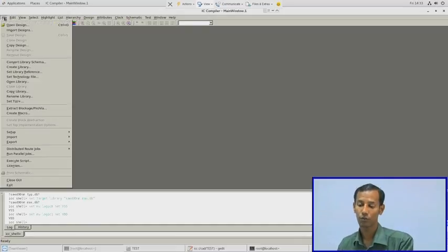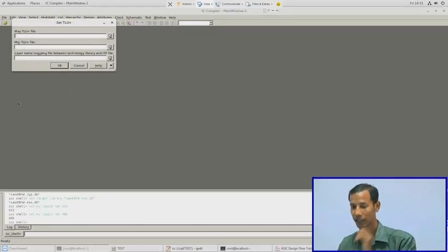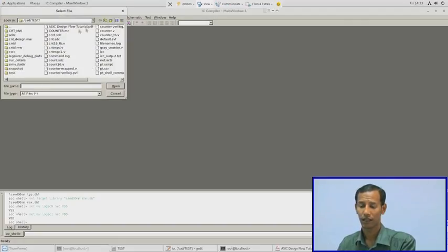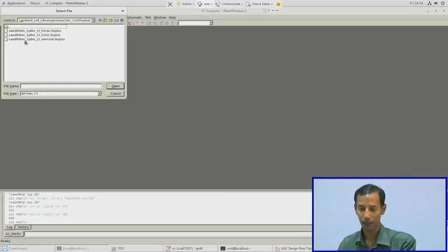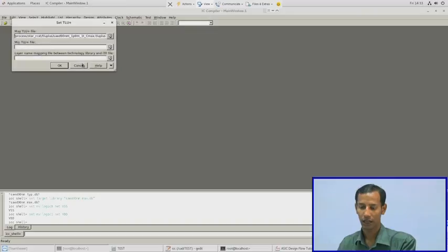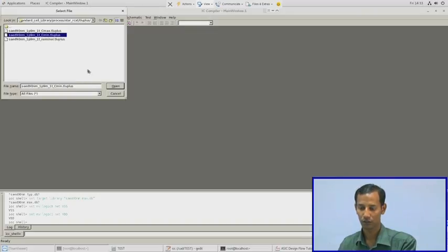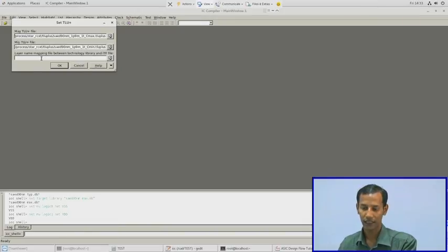After that I have to create the TLU files. These are the additional files, the library information files, which are required by the IC Compiler. You will get these in the technology library itself. In the process, under star RCXT, then TLU plus, here you see this is the max one, and for the minimum choose the cmin TLU plus. Then there is another thing, the layer name mapping file between the technology library and ITF.